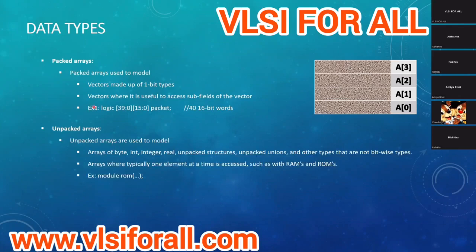The packed array is used to model vectors which are made of 1-bit elements. It starts with 1 bit, and you can make it as wide as you want. It can be 7 down to 0, 15 down to 0, 100 down to 0, whatever you want it to be. It's also useful in accessing subfields. If you want to access 0 down to 10 only, then you can access it from a packed array.